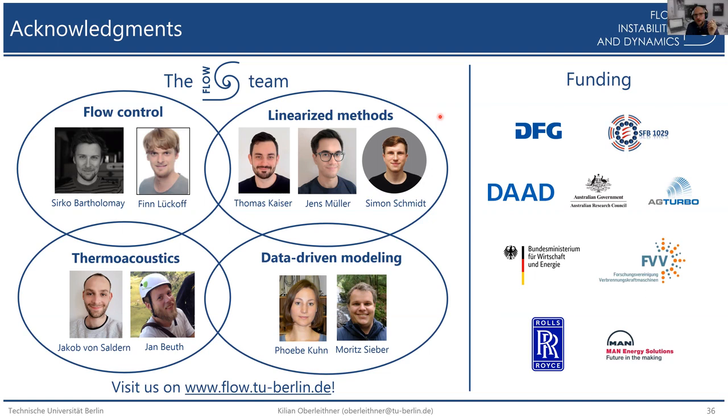Okay. If you really need to have a plug flow, then you cannot use a contraction. As soon as you have a contraction, like in my first slide where you have this rotating honeycomb and then a contraction downstream, that contraction will always generate a hump in your velocity profile. If you don't mind about this, then this is the way to go. If you don't want that hump, then you cannot have a contraction, and then you don't have a top hat velocity profile of your axial flow. Neither of these possibilities is very satisfactory.